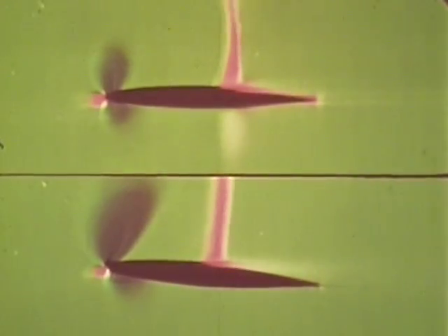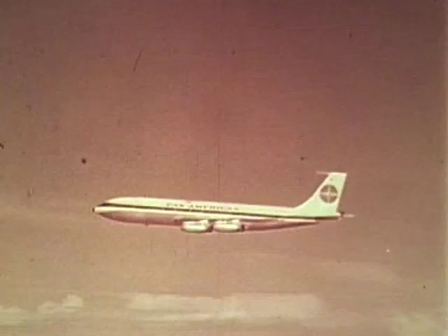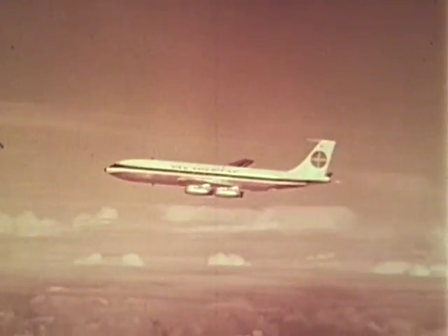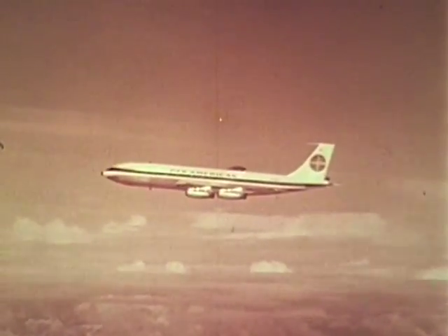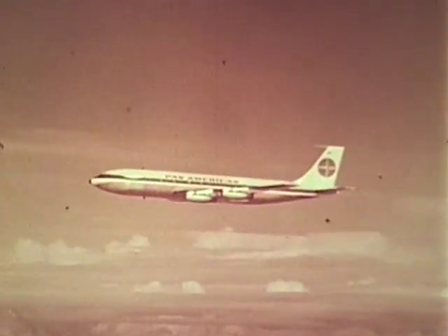How can these troubles be met? We know that two design features, thin wings and sweepback, raise the critical Mach number and postpone the shock stall to higher speeds. Exactly the same features, thinness and sweepback, lessen the effect of the shock stall itself.